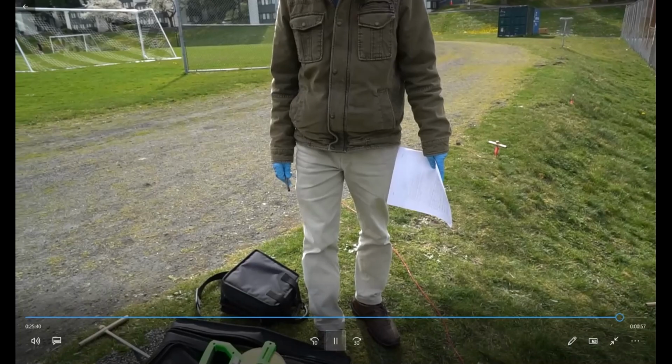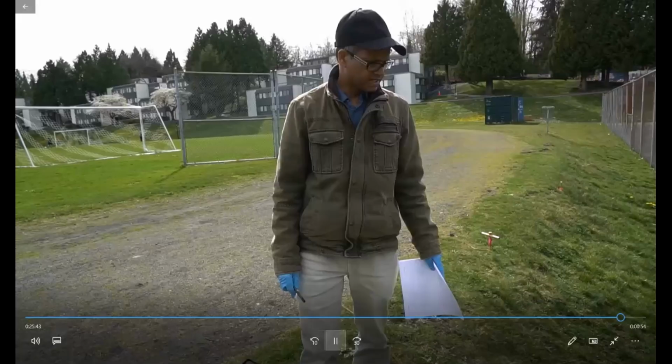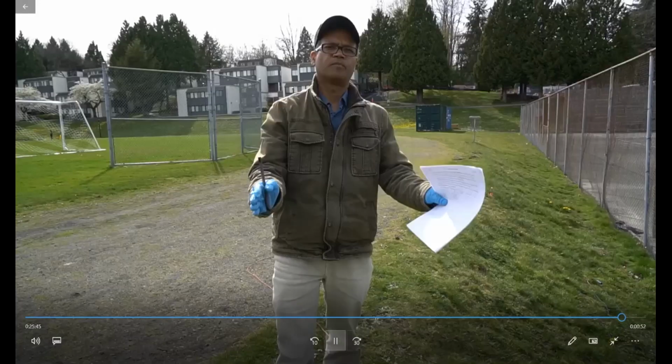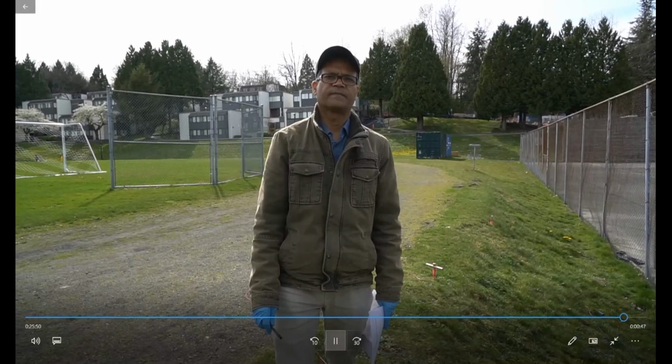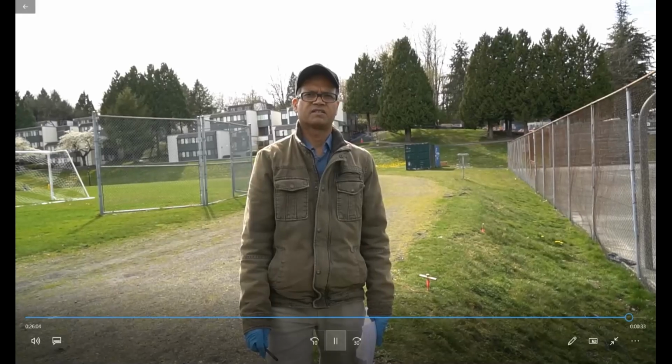Yeah, so that's all in terms of collecting the data. Now all this data you have to put in the model that you will be creating using WinIGS software, and definitely you have to verify and validate your touch potential, step potential, and ground potential rise, all those things. I'll discuss in our lecture class everything related to these labs, and basically related to the grounding and bonding codes all together. And yeah, I'll talk to you on April the 28th.